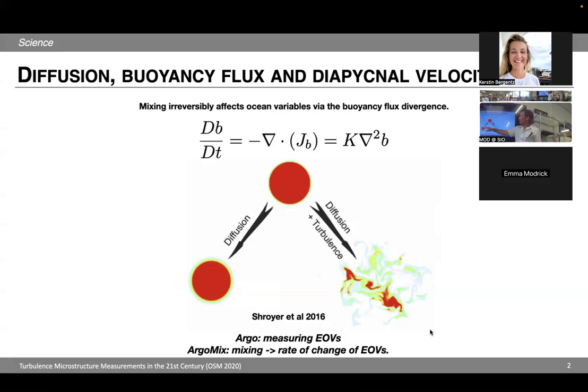Eventually, molecular diffusion will cause that blob to spread. In fact, that's the only thing that can actually cause gradients to diffuse. But because the surface area of this is pretty small, you have to wait a long time. Turbulence is really good at stretching and straining these things out, so the surface area increases and you get this huge thing.